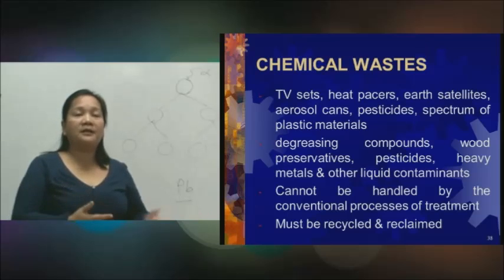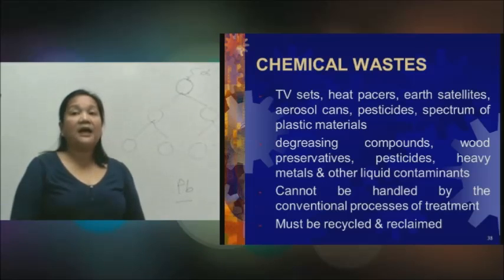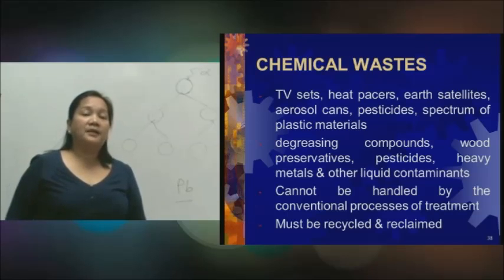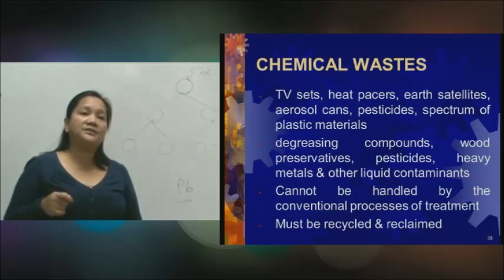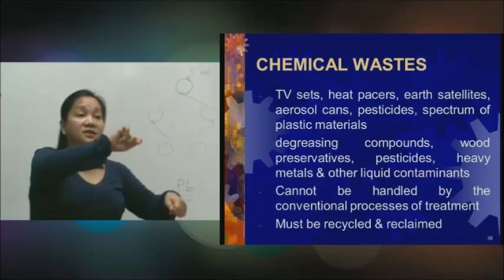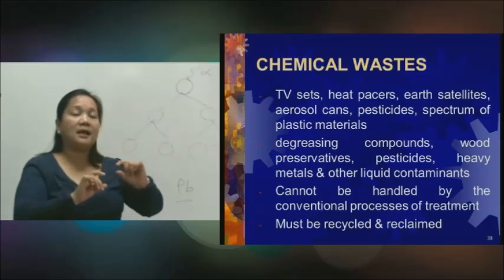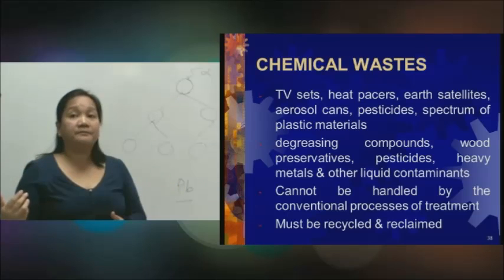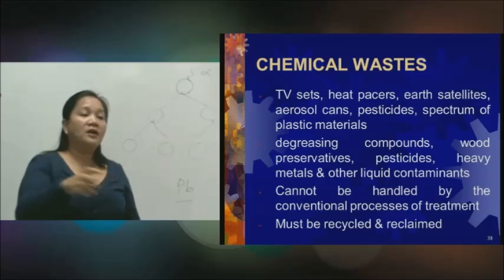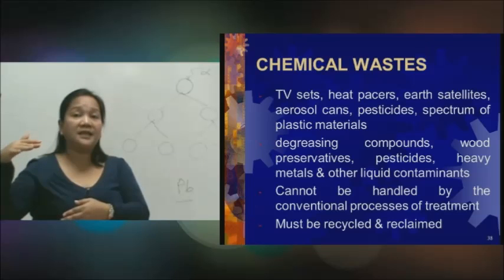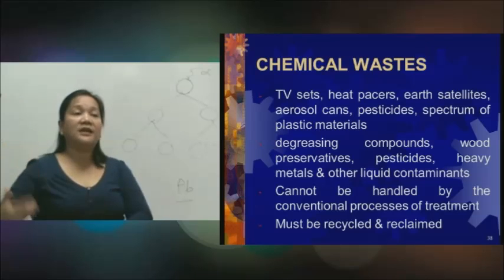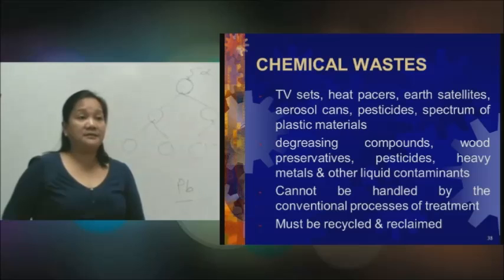Now for example, with respect to the container with the hardened paint, how would you make it an ordinary solid waste? Normally in industry, they spray the hardened paint and then they just contain the hardened paint separately from the container. Now, if you do so, the empty container of the paint is already classified as a solid waste.